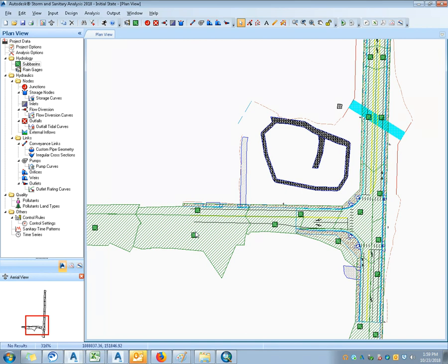Figuring out the quantities, the percentage of impervious. Say you've got a subdivision. Say you've got a pasture right now, and it's going to be an industrial development, so 85% impervious. So it's shown somewhere in the county's GIS that this is going to be industrial development, and there are curve numbers associated with that.